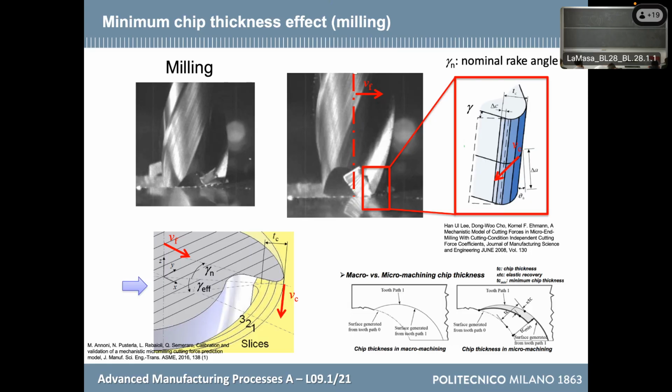The third one, and so on. At a certain point, thanks to the elastic force of the mill that has been loaded by the fact that my cutting head is moving ahead. Moreover, now I have a certain stack of material to remove, and probably I have overcome the minimum chip thickness. Finally, I can remove the material.